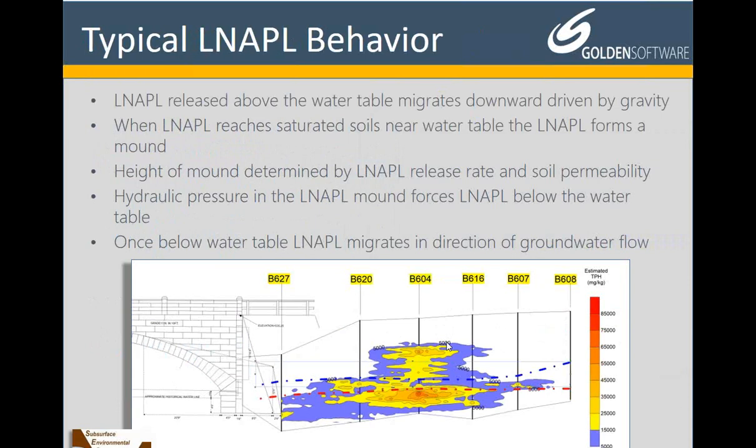We frequently find leaks occurring below the frost line, which in the Massachusetts area is usually around 4 feet. So from that depth down, you'll see some residual contamination, and it is above the water table. There are 2 water tables shown in this image. One is blue and one is red. Those are the historically known high and low at this particular site.